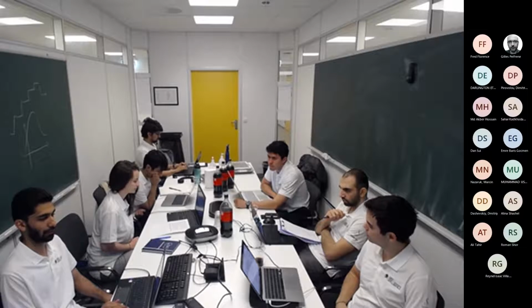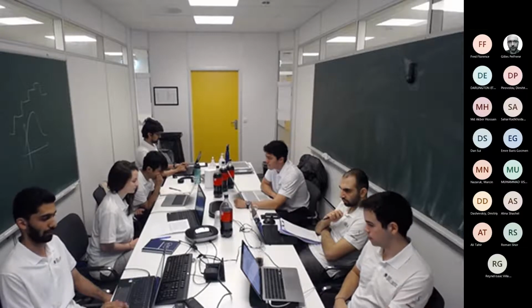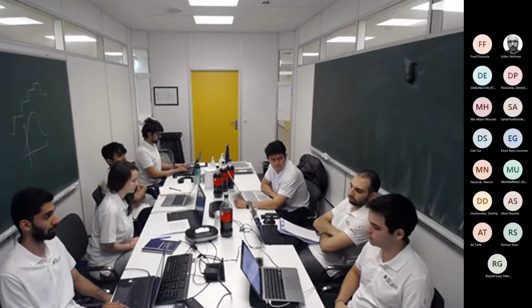For the second part of the reinforcement learning, we plan to use it in managed pressure drilling to optimize a PID controller by tweaking its tuning parameters, as well as suggesting a reference BHP to get a stable dynamic response for the controller. Okay. Elaborate a little bit more.